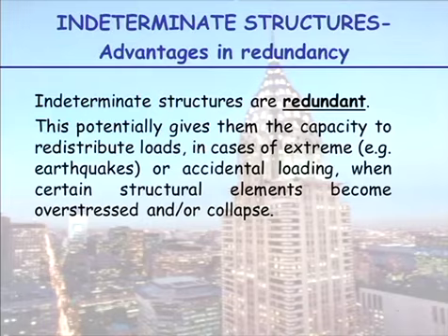So indeterminate structures are redundant. So that potentially gives them the capacity to redistribute loads in case of extreme earthquakes. So as I said, if you have accidental loading, earthquake loading, war loading, and certain members of your structure are removed, then the structure will not necessarily collapse. The loads will redistribute and it will still stand.